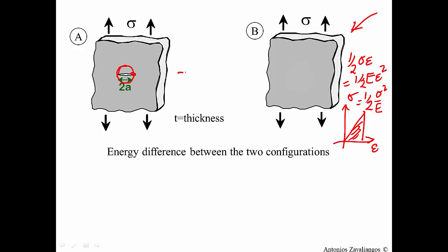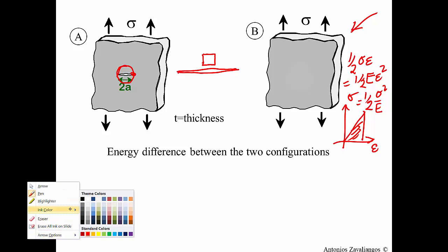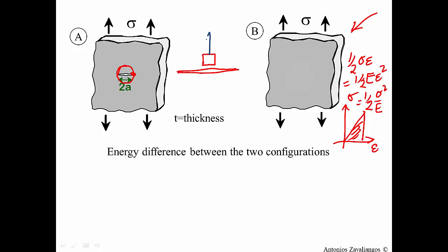If you consider the crack and an elementary volume of the material just next to it, you may be able to see, and you need to think about it, but it's not difficult to convince yourself that the vertical stress, in this case, if our axes are x and y, sigma yy in this part of the material close to the crack is 0.